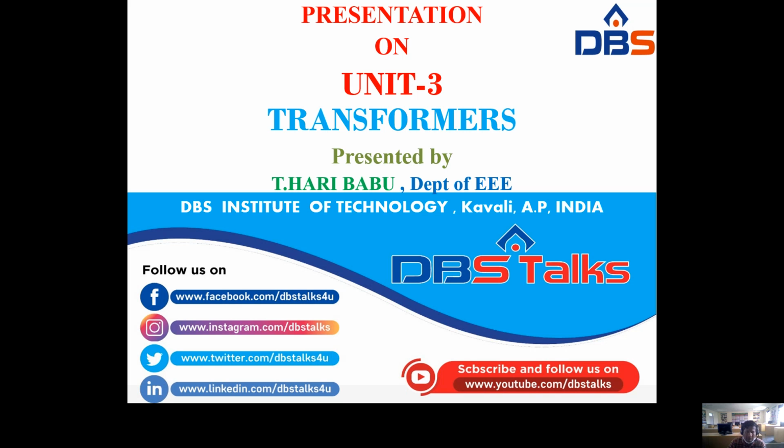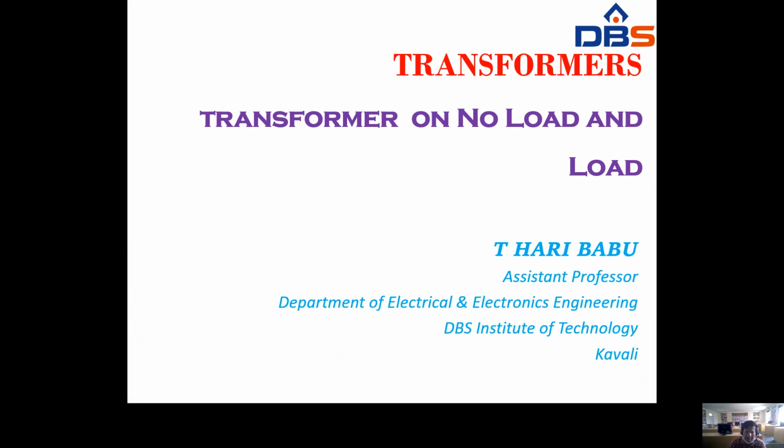Generally, what is a transformer? A transformer is a static device which transfers electrical energy from one circuit to another circuit without change in frequency, with change in voltage and current. The main principle involved in a transformer is the mutual induction principle. That is, it is based on the electromagnetic induction principle, that is mutual induction.